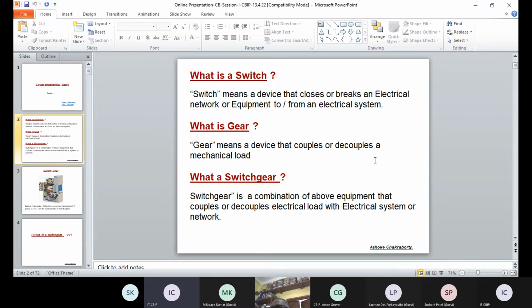Apart from that, there are some kinds of relays which also sense temperature, so you have RTD or PT100 thermal sensors. You have other kinds, like pressure. Say, for example, you want to operate the pressure release valve of a transformer. That is a purely mechanical device there to prevent a transformer from explosion and fire hazards, so it is operated on a pressure switch. That pressure switch ultimately gives a trigger to an auxiliary relay or master tripping relay, which gives the final signal to the breaker through a 220 volt DC or 110 volt DC command. In the switchgear there is a coil known as the trip coil, which gets energized. As soon as it is energized, it hits the tripping bar, the mechanism trips, and once the mechanism operates, the switchgear opens.